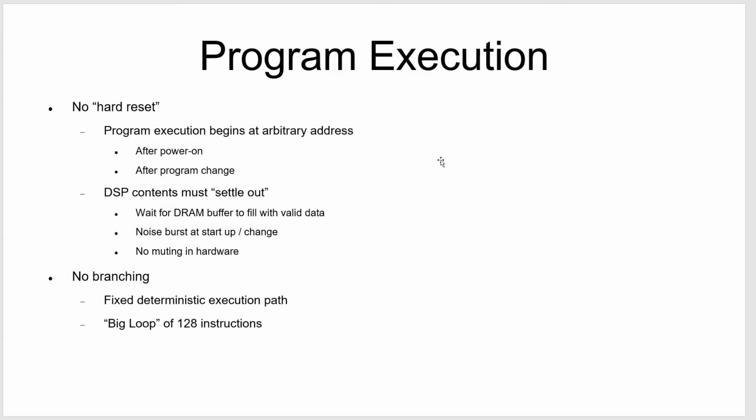So the first thing we noticed is that Keith Barr made it as cheap as absolutely possible. You should have worked at Tandy at some point. There's no hard reset. In other words, when the DSP powers up, we don't have any idea what it's doing, and it just starts running at an arbitrary address somewhere in the middle of the program, which means that when you first turn it on, you're going to get a little noise burst.